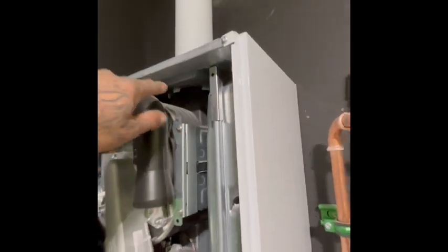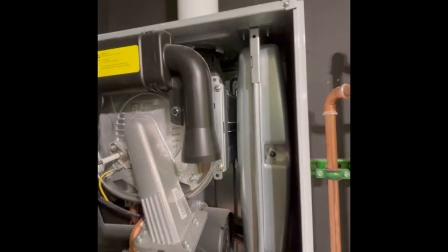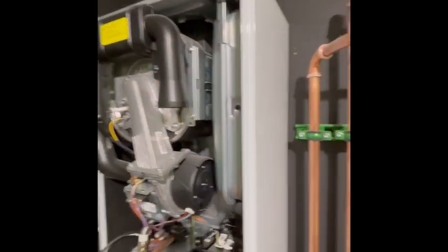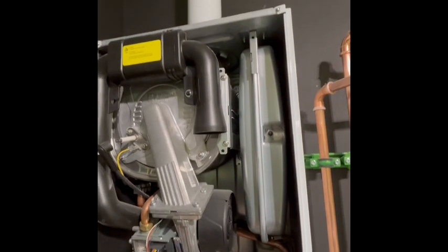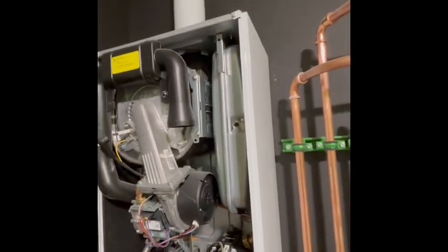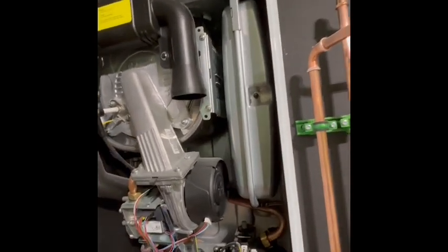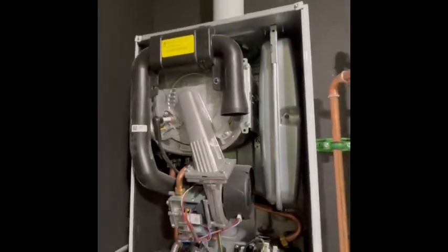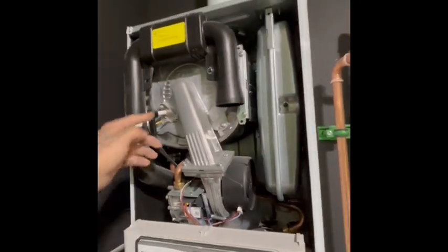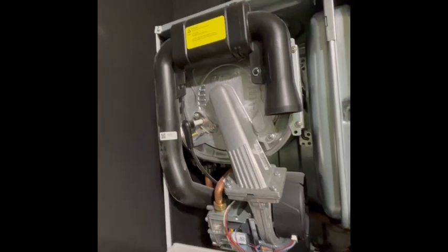Another thing that will also cause ignition faults is if you've got flue seals that have gone. So if that's damaged there, if you're not getting fresh air coming in for combustion, basically, it may work for so long and then it'll go off and cause an ignition fault because the air's vitiated. You've got no fresh air, so the gas burner will start lifting off and searching for oxygen, then it'll come off the electrode there and cause an ignition fault.